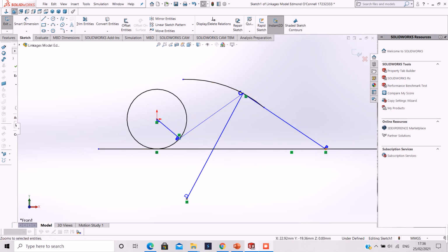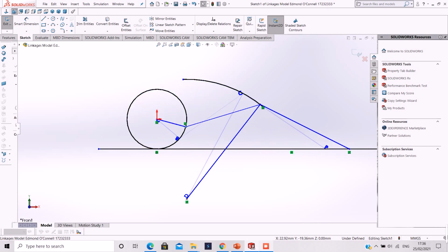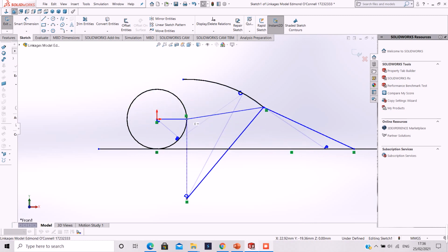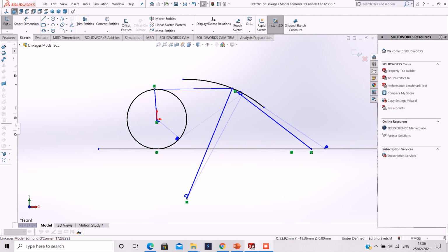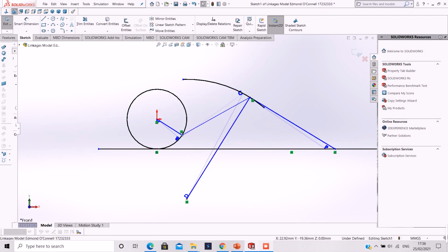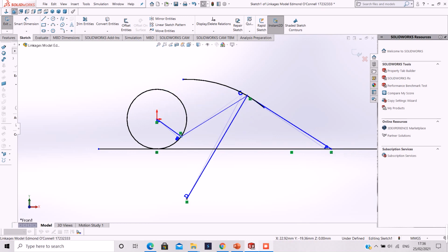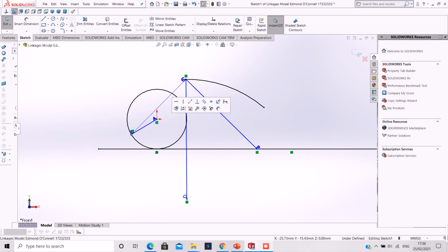So as I move my point B along my circle, the point C will move about this fictional arc, but it won't go any further back or forward. Therefore, my point P will have a maximum and minimum position along my XY line. For this displacement diagram, you can see that point P will move linearly along the line, but my point C will only move about a fixed distance along this arc.